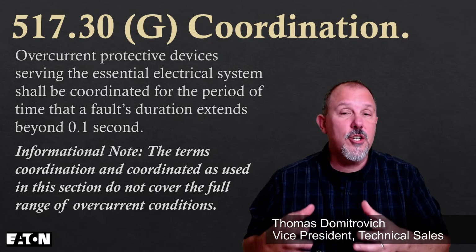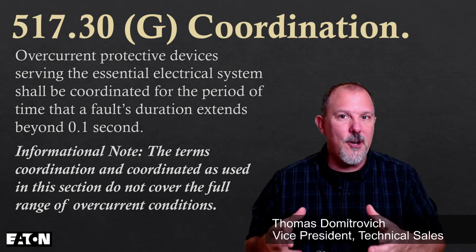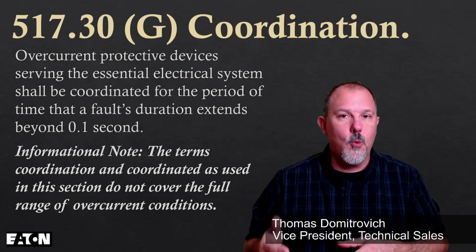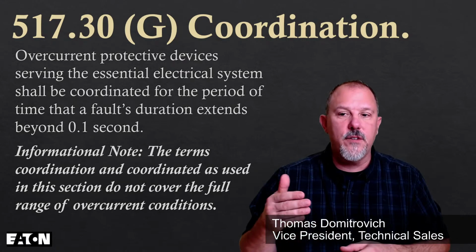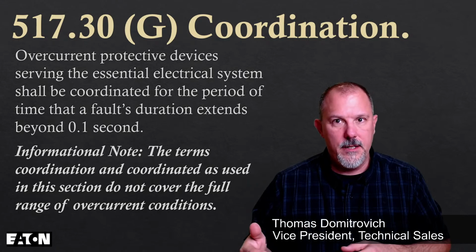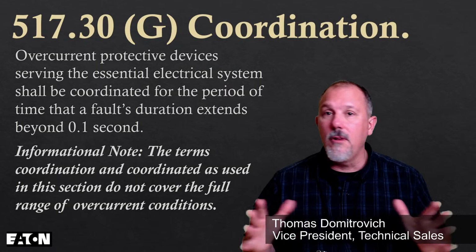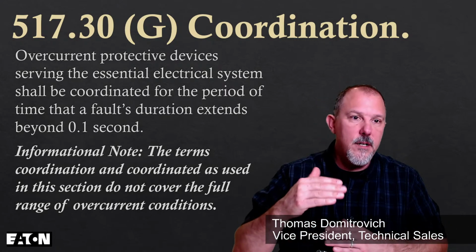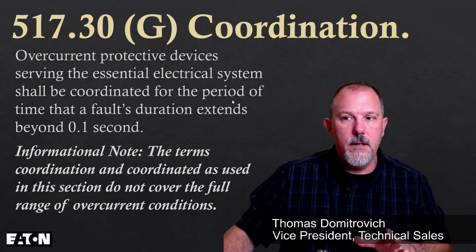Now, the informational note helps you understand you're not really talking about fault currents here. The terms coordination and coordinated, as used in this section, do not cover the full range of overcurrent conditions. The reason they say that is because all you're looking for is separation of curves beyond 0.1 seconds. You're not considering the fault current.